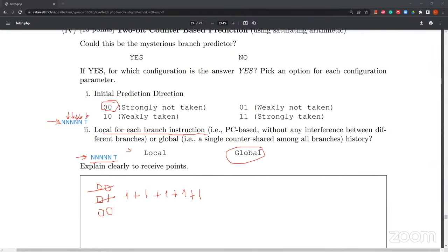And then finally, when we are here at the final instance of this branch, which is taken, we will again mispredict, because when we leave this sequence for the second branch, remember we leave it when the counter is at 1, 0, which predicts this taken branch as not taken and gets updated to 1, 0, right?